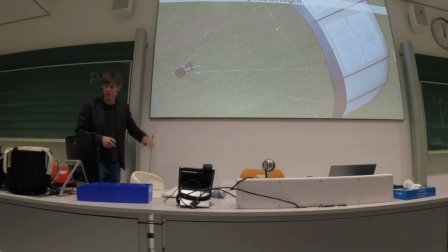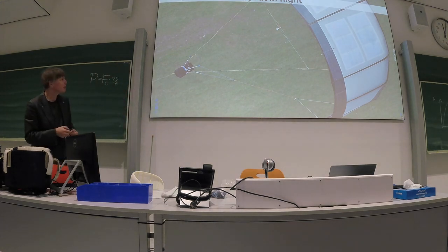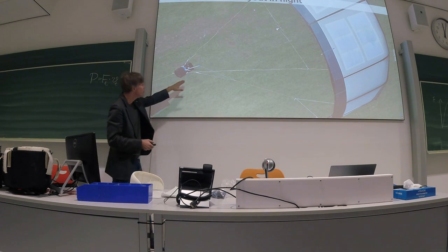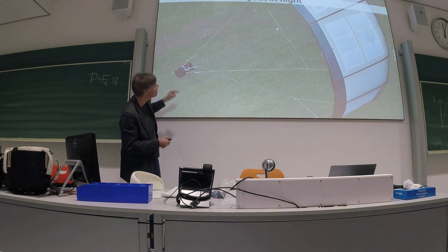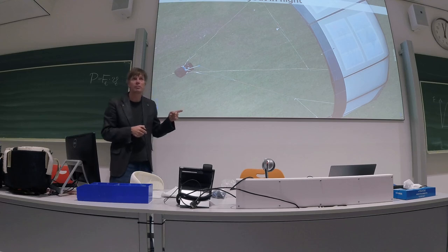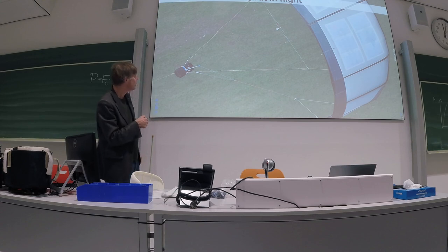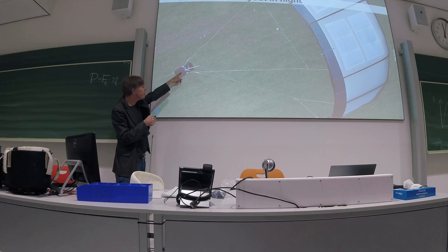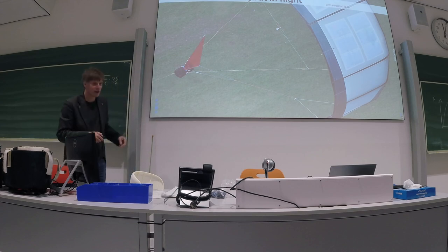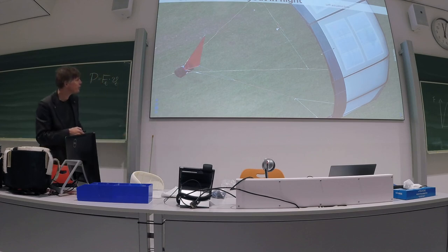So this is the powered and this is the depowered state, and you see that the wing is now pitched down with respect to the tether. And here you see the whole thing in flight. You see the kite flies in this direction, pitot tube and a badminton bat. And you see that the inflow comes from here. You see here the depower tape, the left and the right steering line. Here the two pulleys. You see the left actuation loop and the right actuation loop.